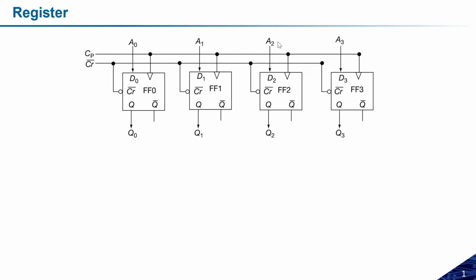But if you want to store a large amount of data, in that case, D flip-flop can serve the purpose, because it is not performing any operations on the data, whatever we have given to the input. If the clock is executed, whatever data has been given will be stored in the flip-flop, and during the next clock, it may be changed. So this is how it is holding the data. If I have to store some data, if I have to make a register and other things, in that case, D flip-flop and RS flip-flops may be used.